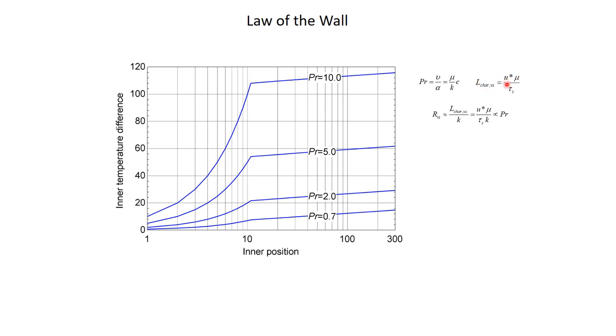We could say it's maybe 5 times that, but it's proportional to that. So that's how far I have to conduct the energy divided by K. And K here is the molecular conductivity of the fluid, because in that viscous sublayer, all I've got going on is molecular diffusion. So this is your biggest resistance, right?